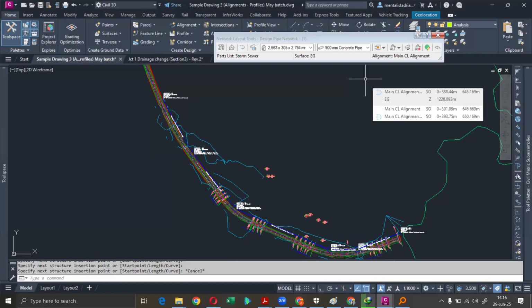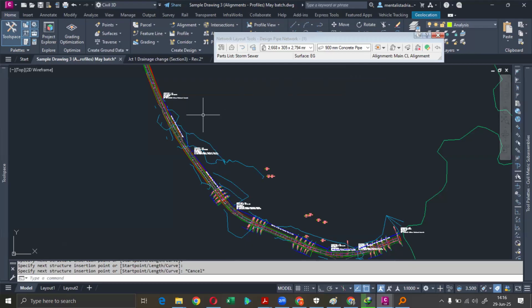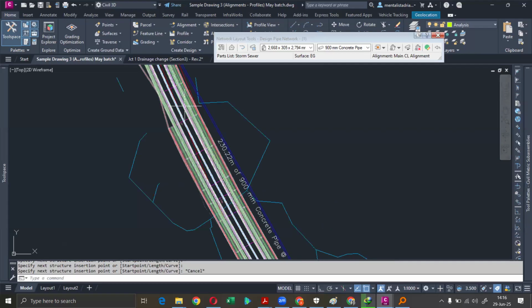You remember, it had that option of creating pipe network from objects. Yeah. But that one, why I didn't use it, because it's automated. And if I show you the manual way, because if you know how to edit the manual way, then the other way is easy. Yeah. So you could have a center line, then just offset that line, then make it a structure.